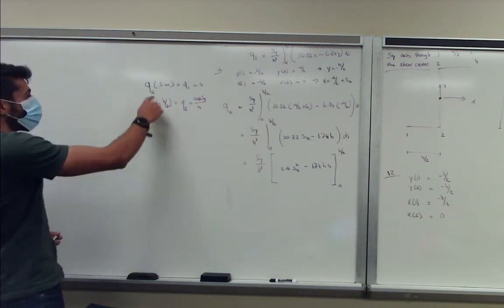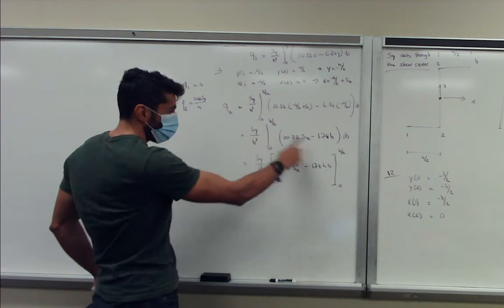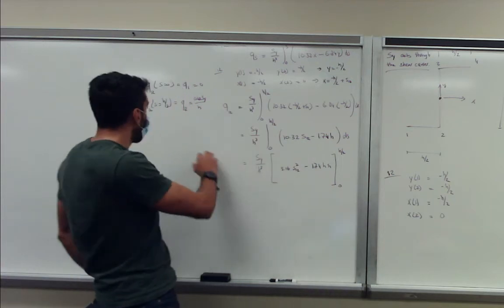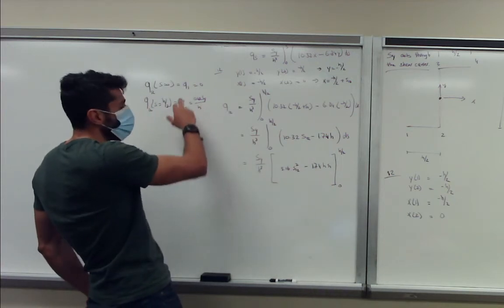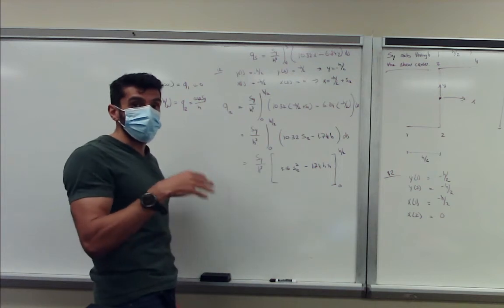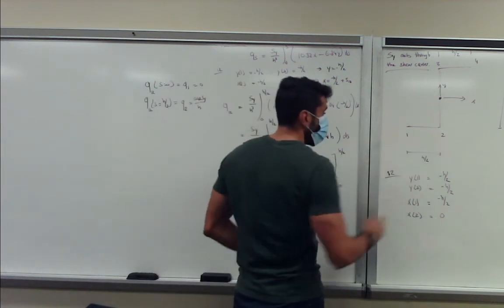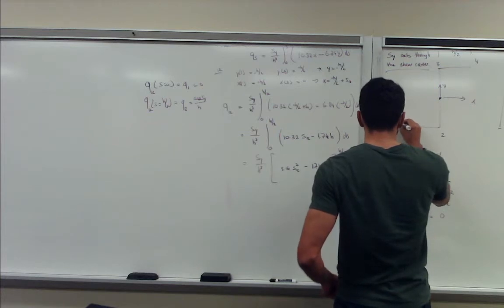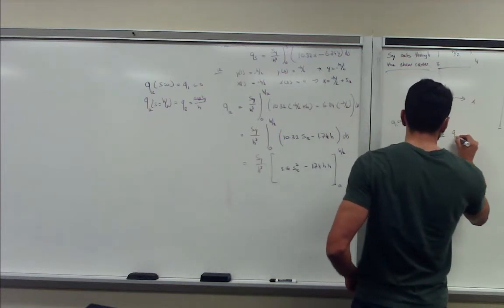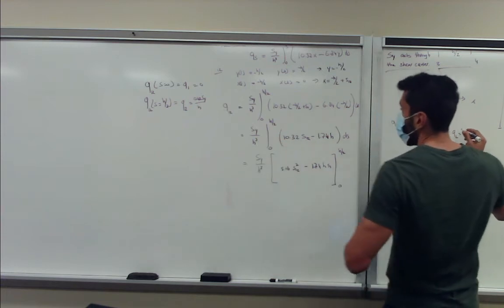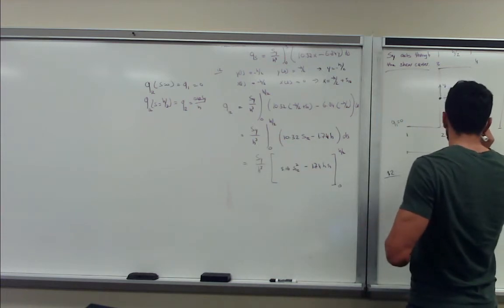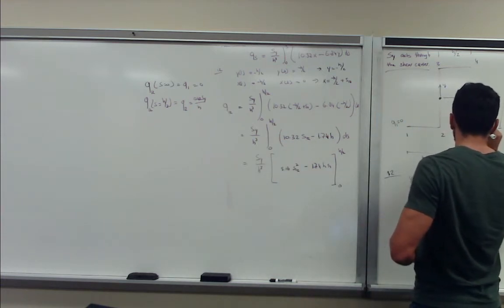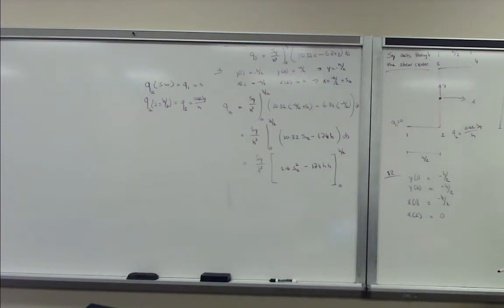So this indicates the shear flow equation along that path, and Q1 and Q2 indicate the shear flow evaluated at those locations. So Q1 would be 0, Q2 would be equal to 0.42 over h, sy, and then we can evaluate Q3 and Q4 as well.